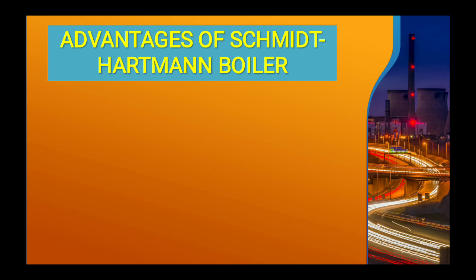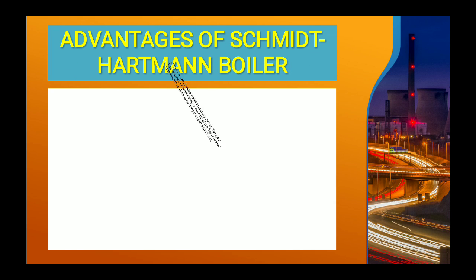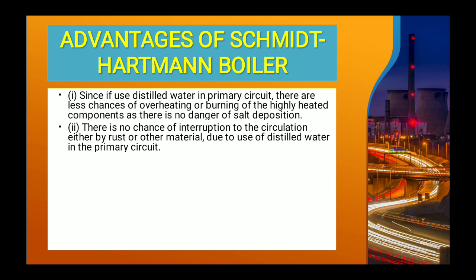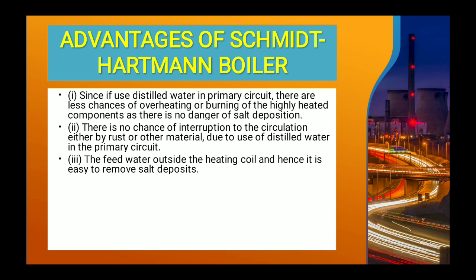Now the advantages of the Schmidt-Hartmann boiler. Since we use distilled water in the primary circuit, there is less chance of overheating or burning of the highly heated components as there is no danger of salt deposition. If salt is present, then the surface heats very quickly. So this overheating problem can be eliminated by using distilled water. There is no chance of interruption of the circulation either by rust or other materials due to the use of distilled water. The feed water is outside the heating coil and hence it is easy to remove the salt deposit.